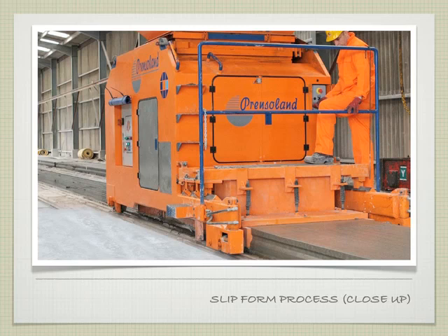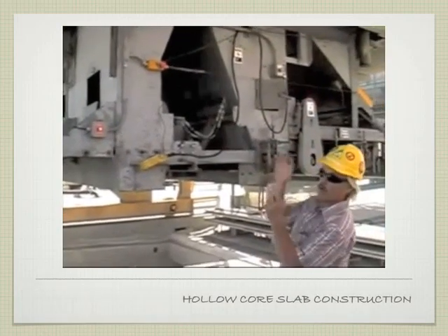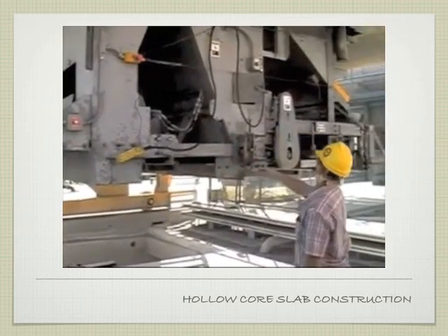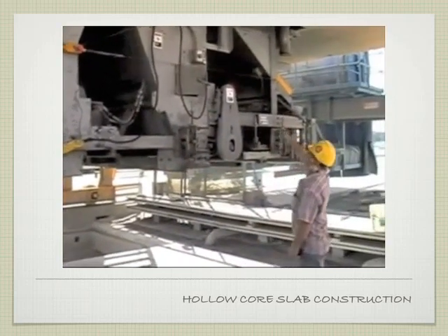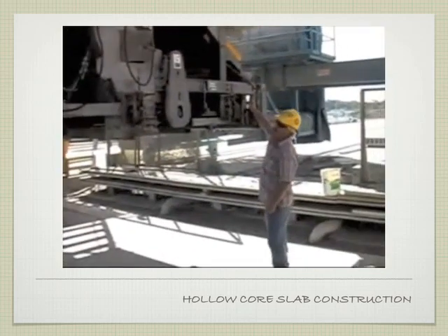So in this particular example, this is a close up of that photograph. We have the reinforcing under here. We're working down on top of that. The hopper is pushing the concrete into those formwork. The slip forms are along in here. They get moved along as this process goes on. Steel bin, and it has doors that open and close. This is the bottom, this is the middle, and over here is the top. And the top would leak into here, actually.